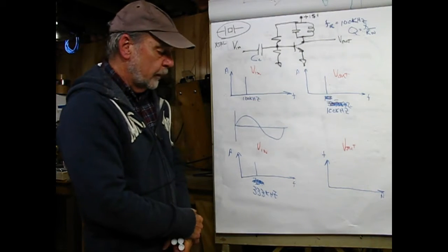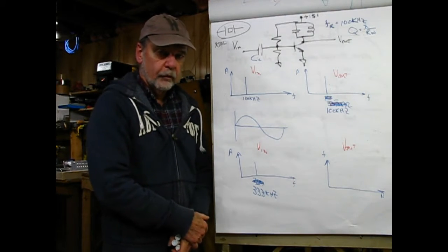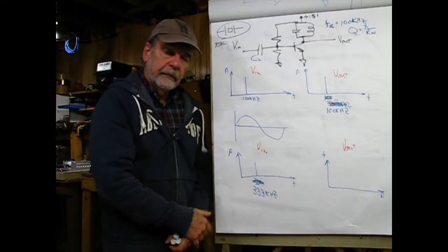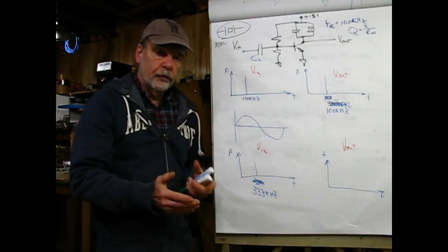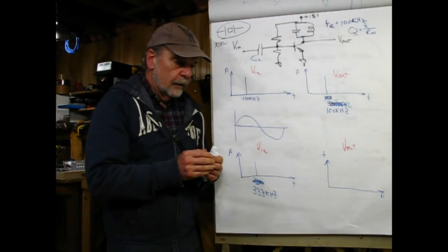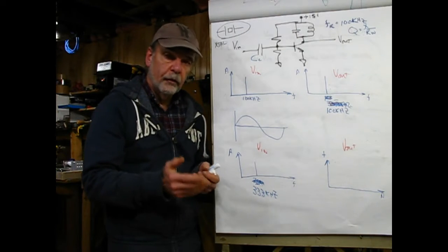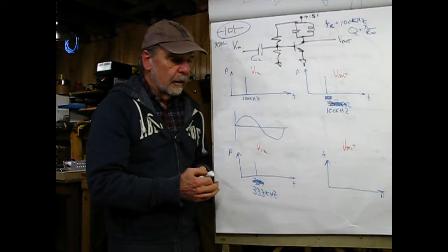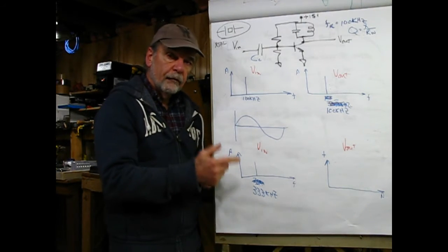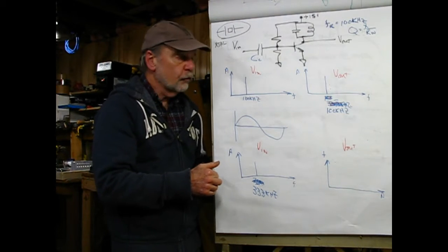Well, many times we need to have very stable frequency sources, say in radio and microwave equipment and so forth, and the way we would do that would be with a crystal oscillator. Now the problem is that as the frequency increases, the physical size of the crystal gets very, very small. It's hard to maintain accuracy, it's very delicate, and also very expensive. So we can obtain that accuracy if we use a lower frequency crystal and figure out how to multiply that up to the desired frequency of interest.